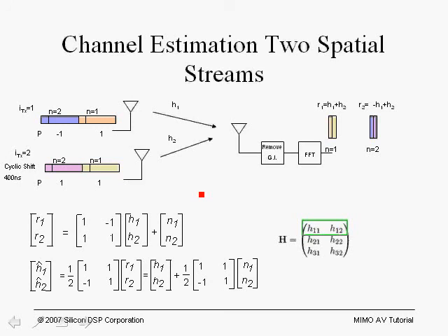In this case, on a per carrier basis, each carrier, for example the carrier on the transmit chain number 1, goes through a multi-path fading channel and is received by the receiver. Assuming flat fading, it is multiplied by a complex number H1, and the carrier from antenna number 2 goes through a multi-path flat fading multiplied by a complex number H2. They are combined at the receiver, so at the receiver you have the carriers multiplied by H1 or multiplied by H2. Now the carriers themselves for the training field have magnitude equal to 1. For a 20 megahertz system we have 56 carriers.